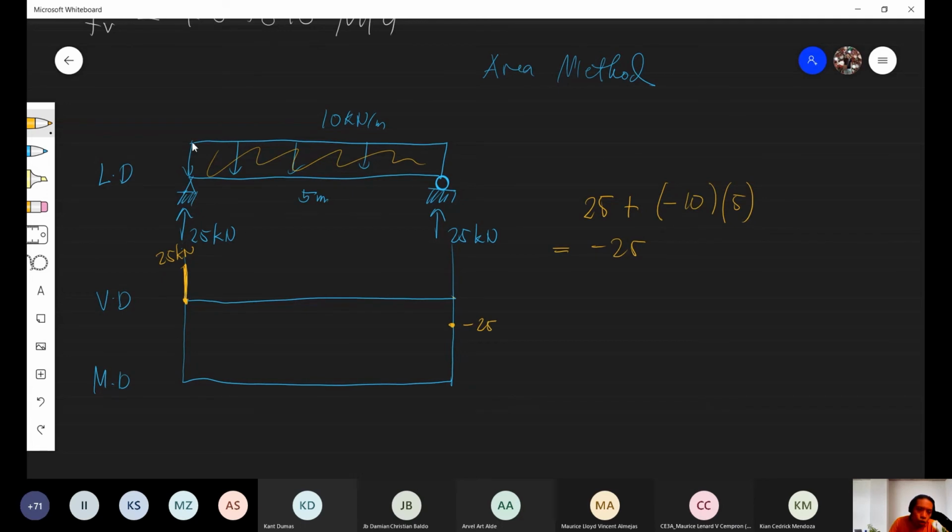If it's a horizontal line, whether in a load diagram, a shear diagram or a moment diagram, let's denote the degree of that line as 0. So in the next diagram, the degree should increase from 0 to 1.